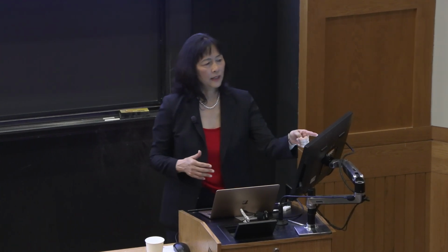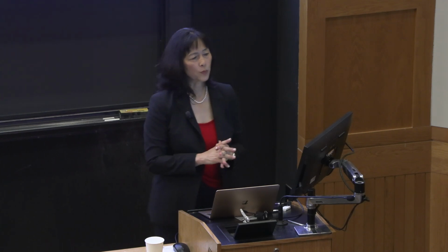And then to get that intersection correct, the speed of the edge flame depends not only on the displacement speed of the progress variable and of the mixture fraction, but it's weighted by this variable k, which is the inner product of the normal vectors, a little bit of geometry, normal vectors of the progress variable and mixture fraction isosurfaces. And so if we combine all of that, we get how fast that edge is propagating.